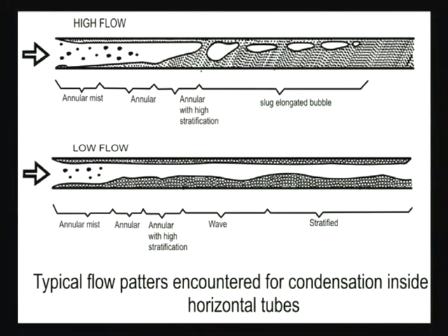If a situation can be made such that the rate of bubble generation at the walls is very high, then probably we will not get a bubbly flow pattern at all during evaporation. We will directly, straight away, go to the slug flow pattern. Such a situation can also arise. So, therefore, which flow patterns are going to occur and what will be the range of occurrence of the different flow patterns depends upon the inlet conditions, the other hydrodynamic conditions and so forth.